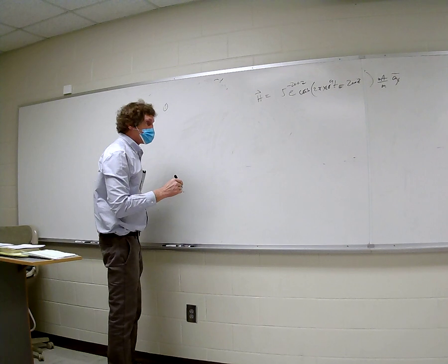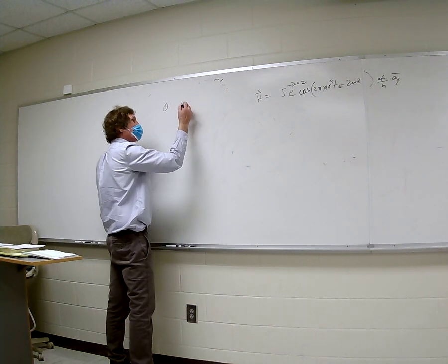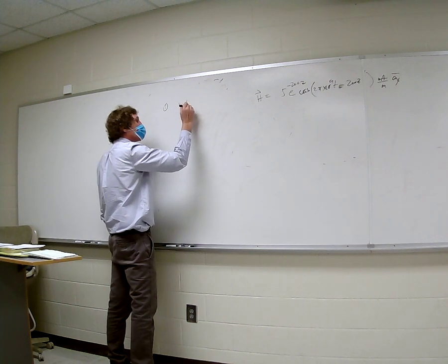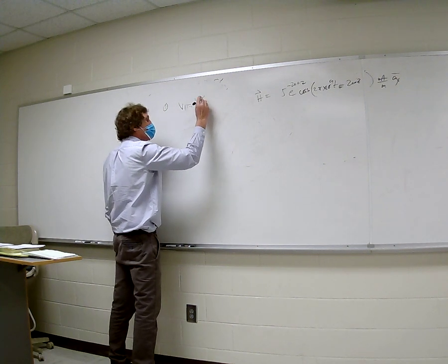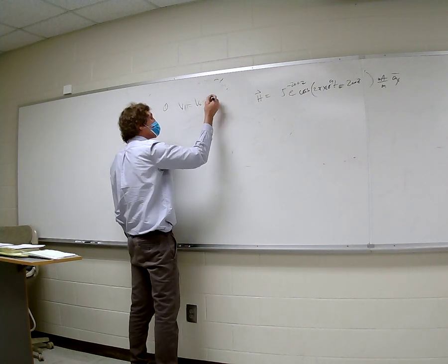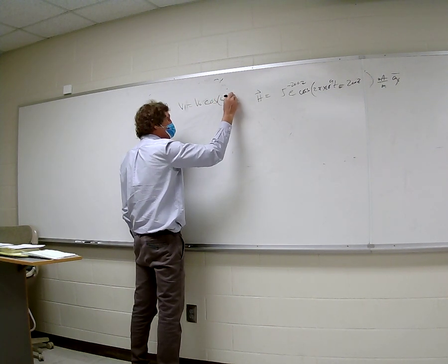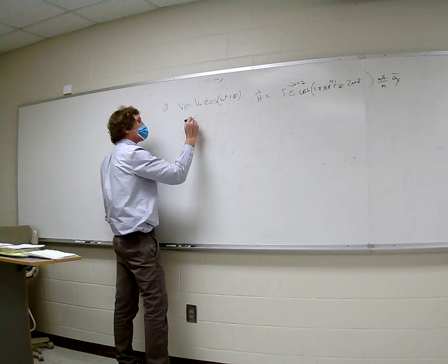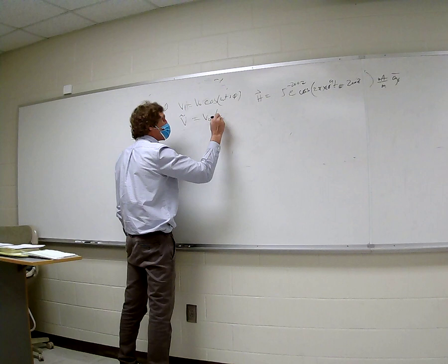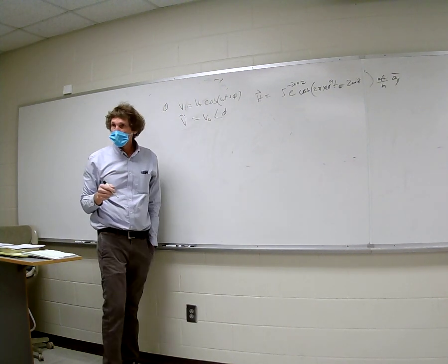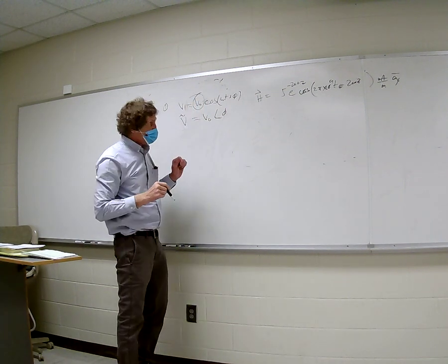Remember, for the phasor domain in general, I want to relate this to the circuits model. If you had V in circuits equal to a magnitude V naught cosine of omega t plus some phase angle, and you wanted the phasor form, you would take the magnitude and put it down here, with the angle phi. Are you with me? Now, what this really represents is the real part.